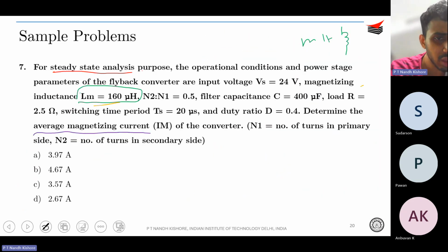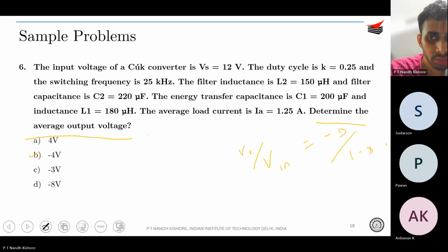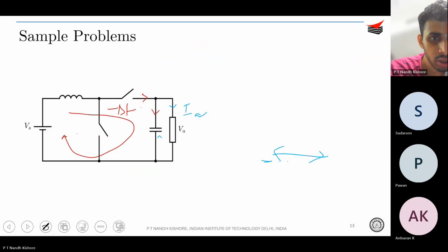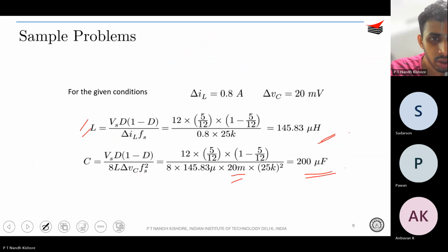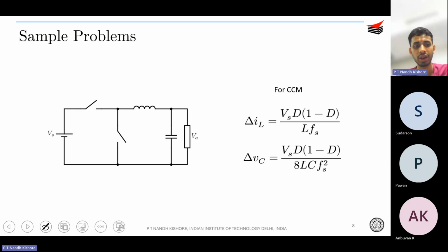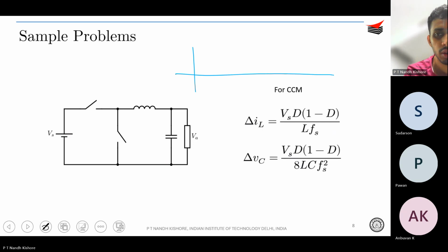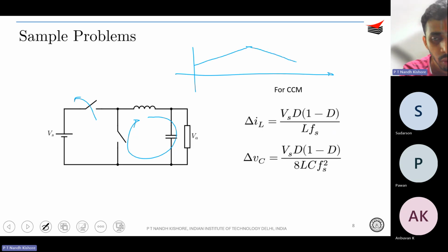If we go back to the circuit, any circuit, right? Okay. So if we go back to this circuit, for example, what they will do is you have your inductor current which is rising. Once it hits I max, they will turn off the switch. Okay, so the inductor will discharge. When it discharges, the inductor current falls down, falls down. When they see that it has hit I min, it has hit this point, they will again turn on the switch.